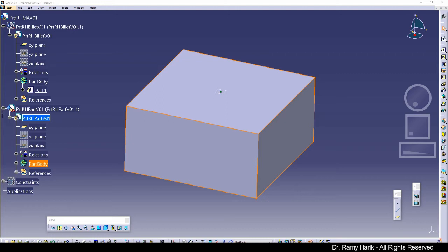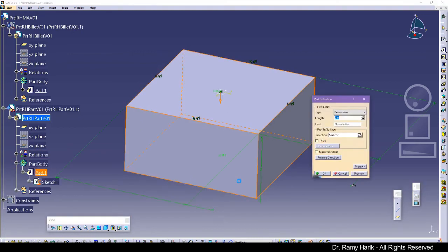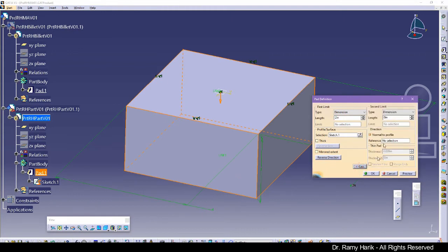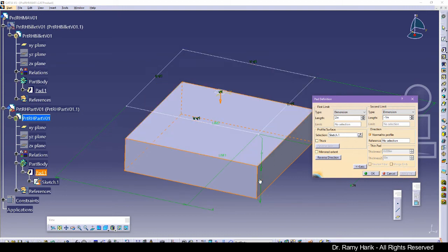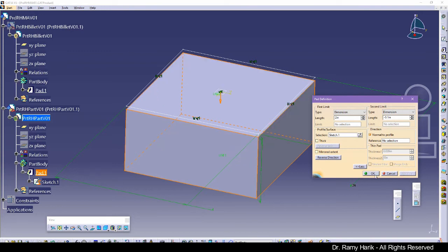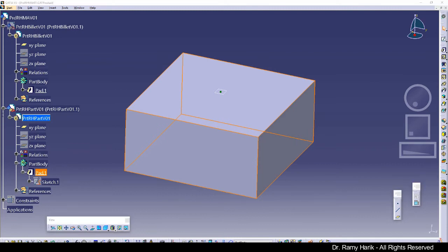So the first thing we're going to do is some surfacing operation and remove 0.1 inches. The way that we do it, we click more, and in this second dimension, I'm going to demonstrate this one. I'm going to put -1, and you're going to see how it moves, this length is going to become 1 inch. So this is what happened. Now we don't really want to remove a whole inch, we just want to remove a little bit, so we're going to remove 0.1 inch, and you see how much it goes from this plane to this plane, and this is to do a surfacing operation at the start. So that's the first thing.